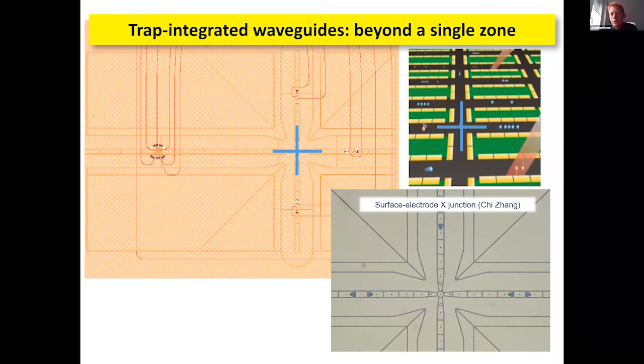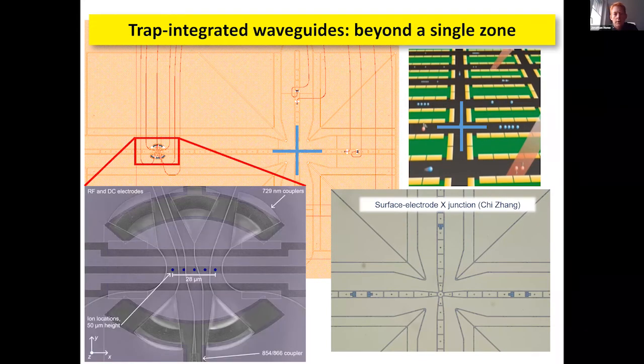There's the junction, which was designed by Qi Zhang. But also we have a region here where there are 5 couplers, which all are intended to create a tight focus at individual ions. And so we've characterized the optical fields from that, and you can see there 50 microns above the chip, there are really these nice 5 tight focuses, which hopefully once we're able to use these systems, we'll be trapping in that system and addressing these ions individually.